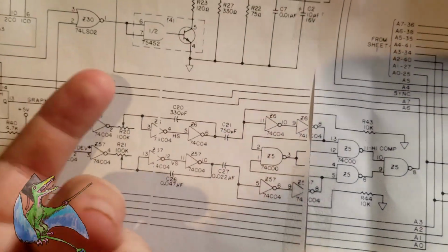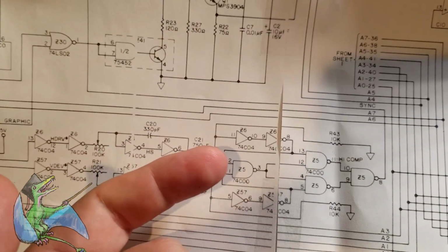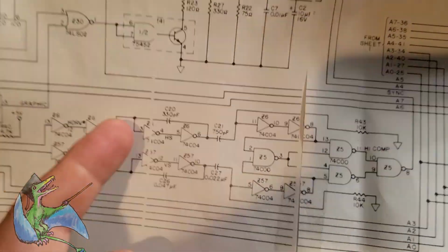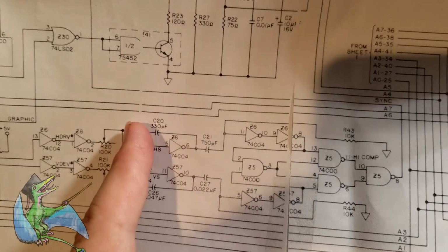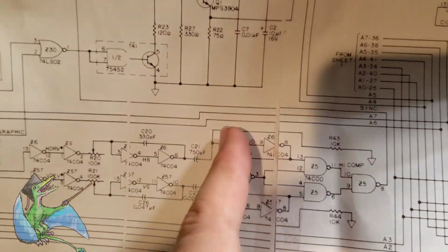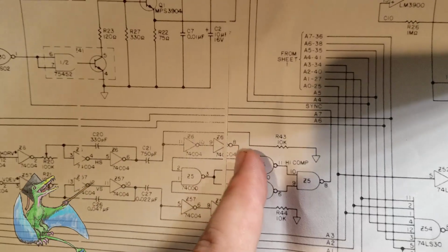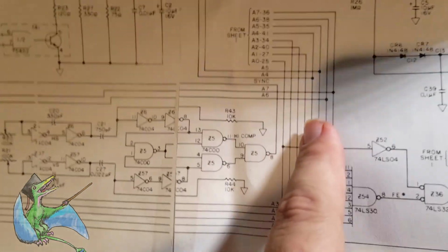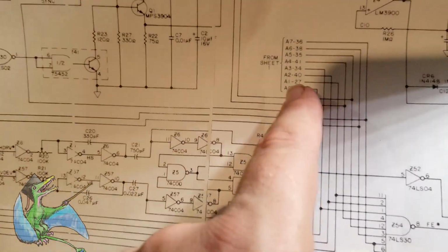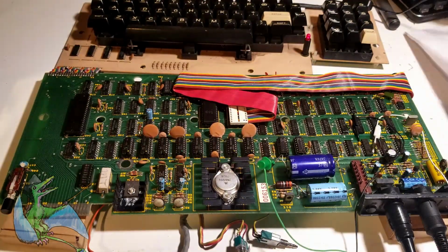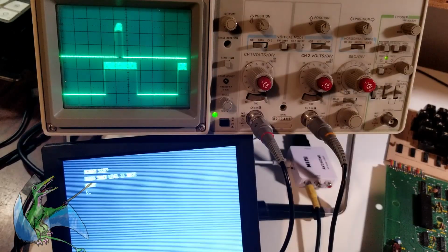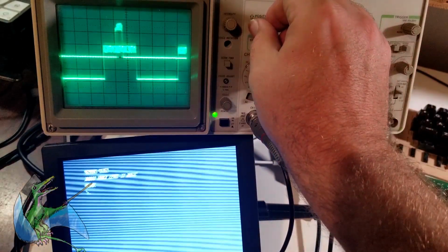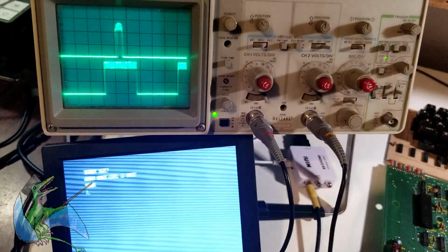So we're essentially seeing a cleaned up version of what goes into the circuit over here, where we delay and pulse stretch. We're seeing what is actually fed out into this circuit, which mixes it with the vertical pulse and creates the composite sync signal that ends up going up here. So let me go ahead and reposition the camera and show you what the oscilloscope sees there. Okay, so here we are seeing the scope on the screen.